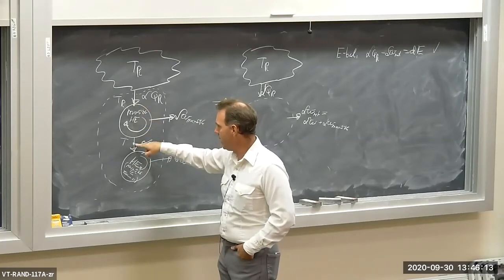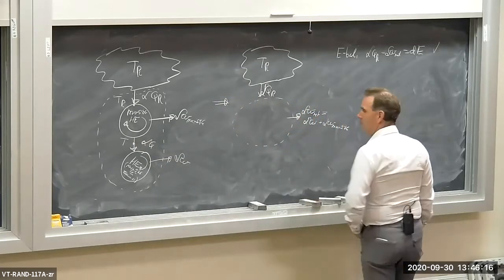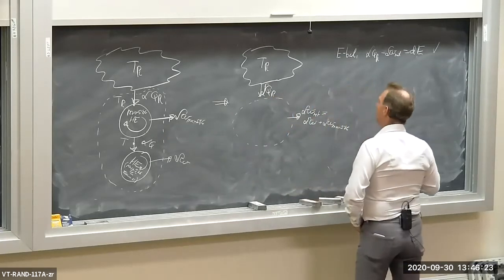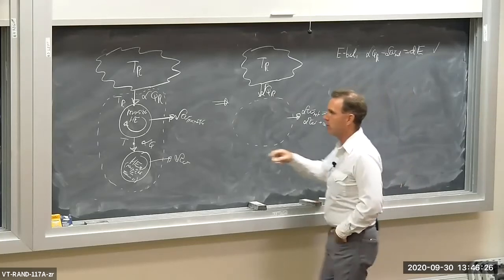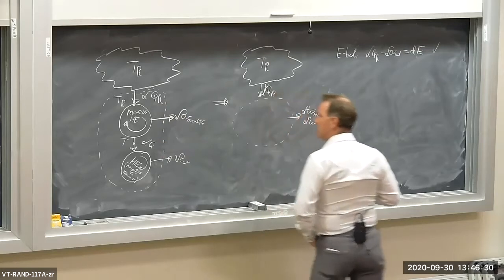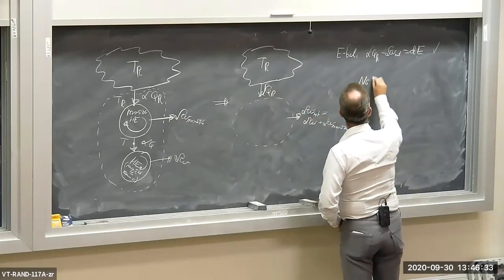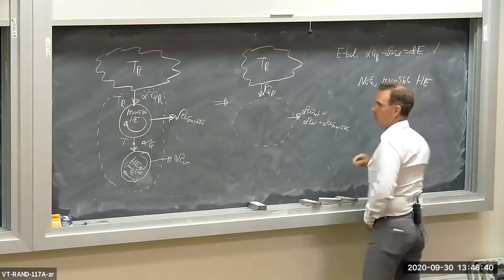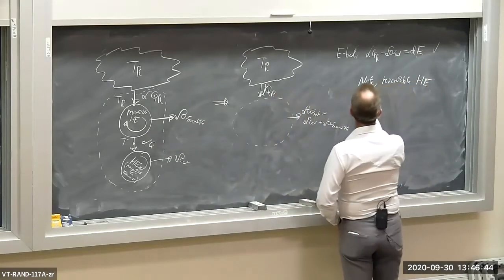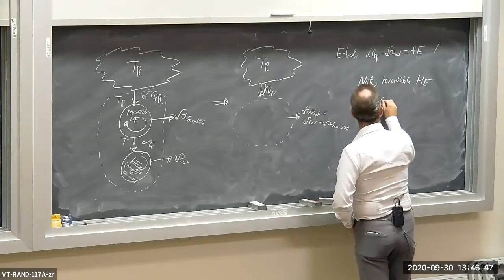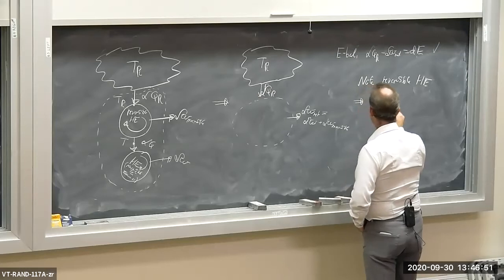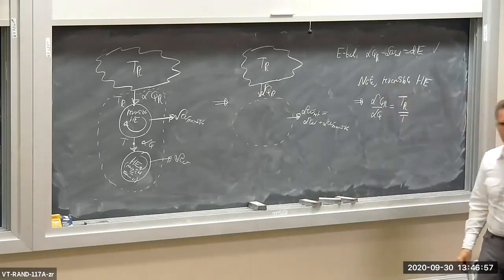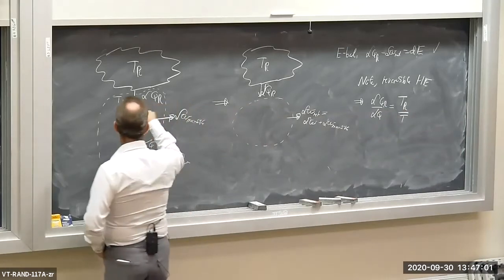We have the reservoir temperature and we have the temperature T. Because this one is operating reversibly, we get that the ratio of the heat transfers, del QR over del Q, for a reversible process, is equal to TR over T. Okay, a reversible process going on here as far as the reversible heat engine is concerned.